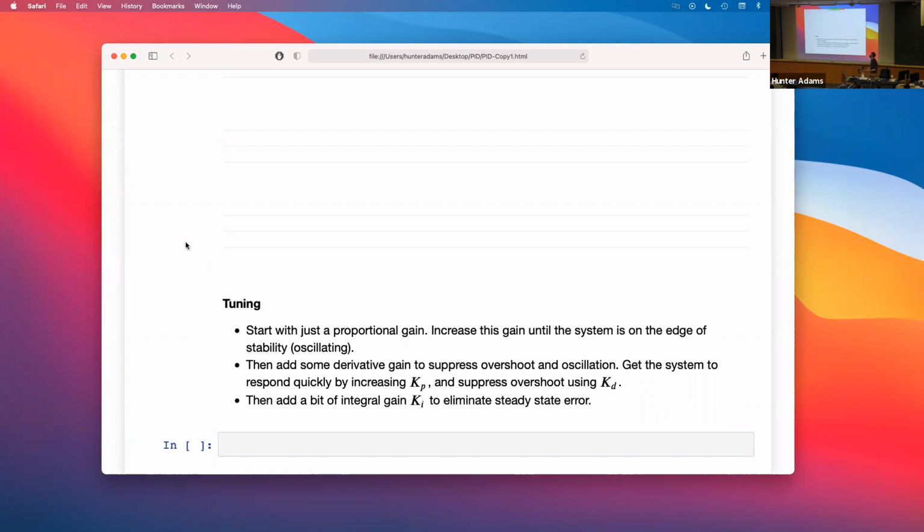You're doing a couple of other things in that ISR, including sending the measured ADC value out to the DAC so that we can look at it on the scope, and also low passing the PWM command and sending that out to the DAC so that on the DAC at the same time we can see the motor state and the control input. I'm going to talk about that low pass filter next time. There's been a little bit of confusion around that, so I'll talk about that next time.